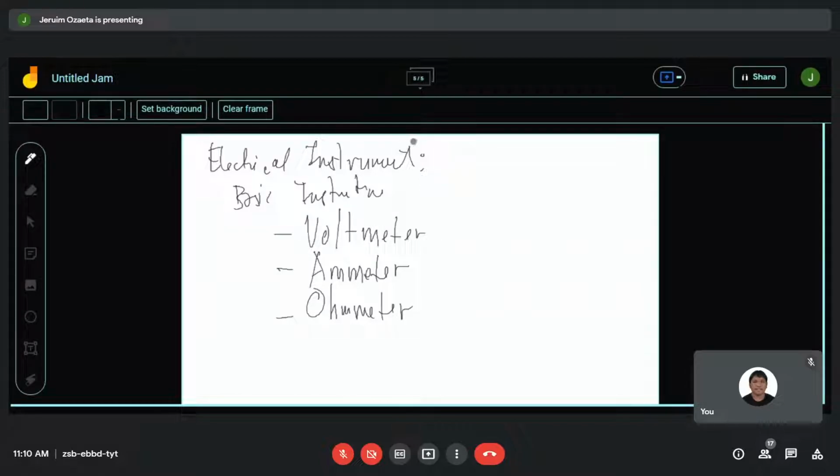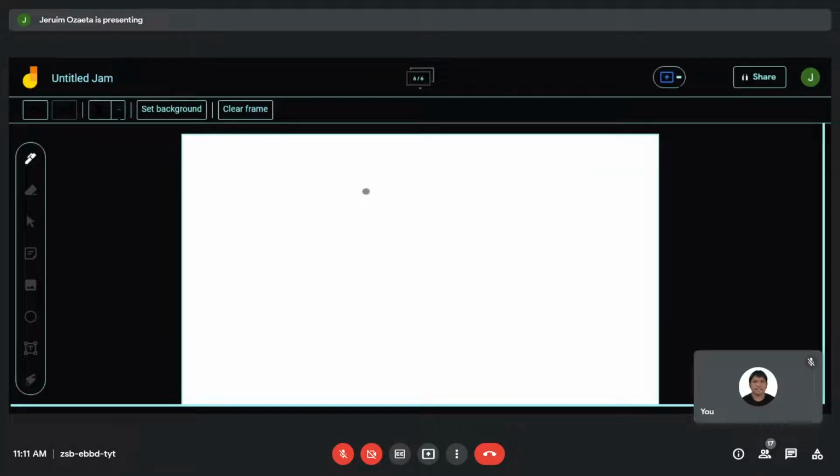Remember that in every electrical network, whenever current flows in a network, in a conductor, the current is always accompanied with magnetic field. Okay? It is always accompanied with magnetic field. So, it is possible to measure the quantity or the magnitude of the rate of flow of current by measuring the magnitude of the magnetic field that is created. Right?